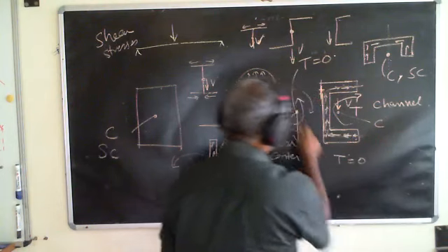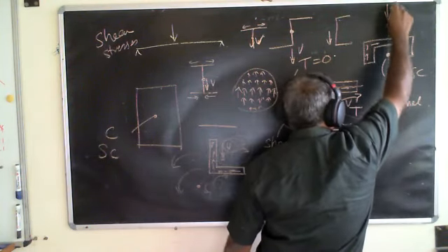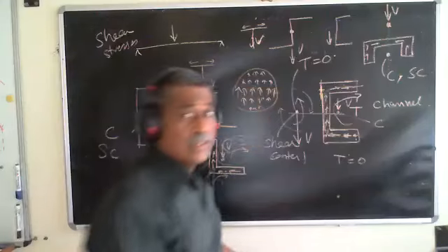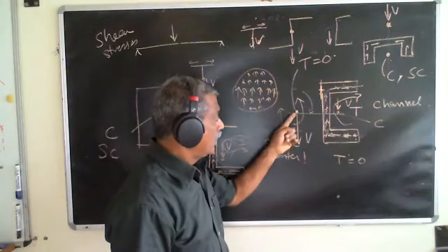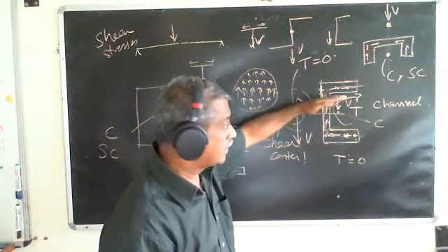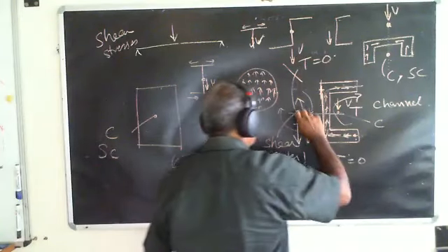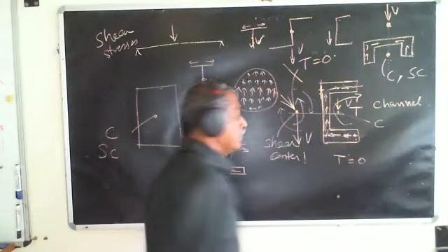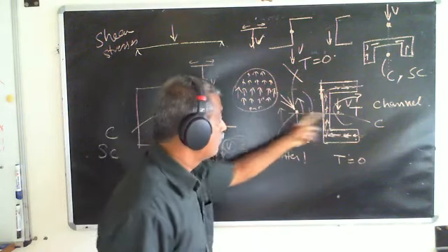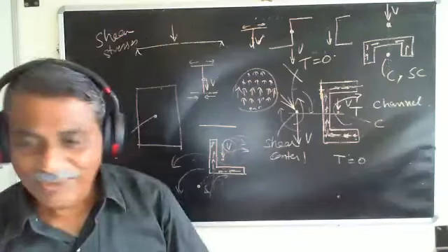If you look at this is here, and therefore if I apply load like this on the shear center, it remains the same, right? And if I apply in the other configuration, it should be the same. If I take any other orientation and I apply the load, I should apply on this shear center, because this is an intersection of this and this. So far, so good.